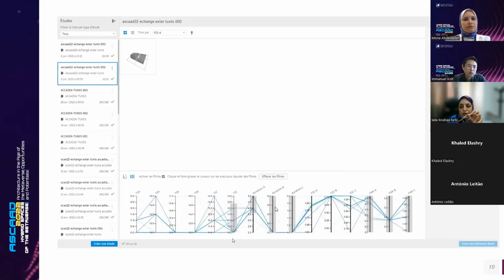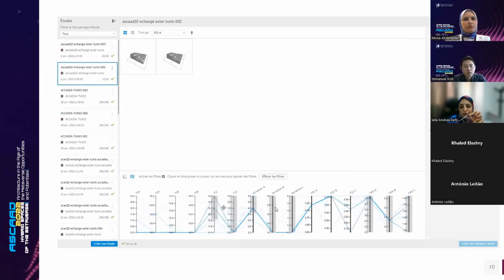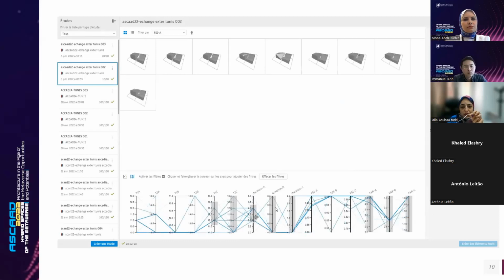The outputs are the FAR and the FSI urban density indices and the shading cut-off time duration. These inputs are represented by a diagram axis and 3D solutions are generated. The generative design makes it possible to generate a digital model of different density solutions by varying the solar access duration.